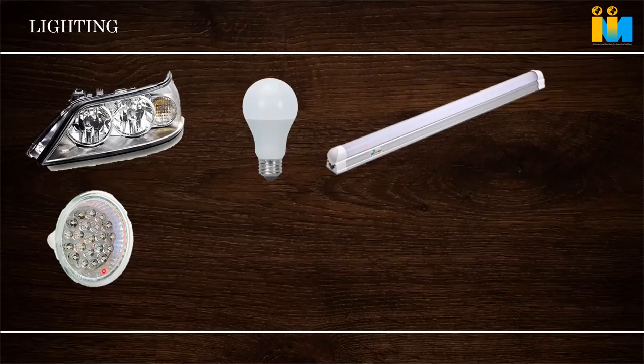And here it comes in applications like LED lens. Lenses are thick parts. Optical grade polycarbonate is generally used. Sometimes PMMA is also used for a lower type of application. But here molding is very, very critical because it's a thick part. Some lenses are 20 mm thick. Then it calls for a different type of injection molding, known as injection compression. The machine itself is a customized or different type of injection molding machine.